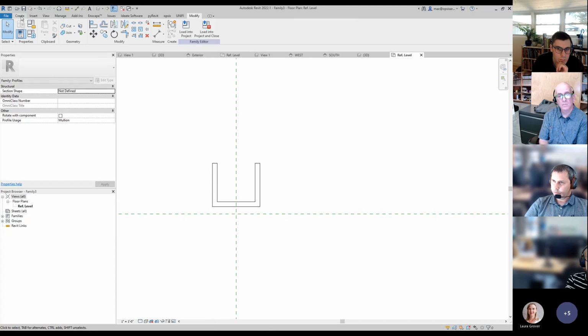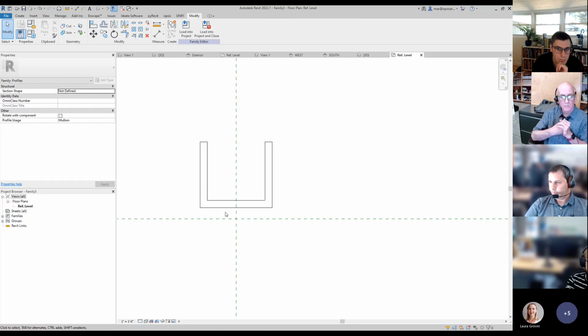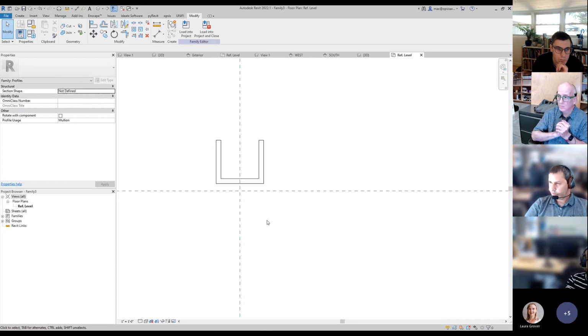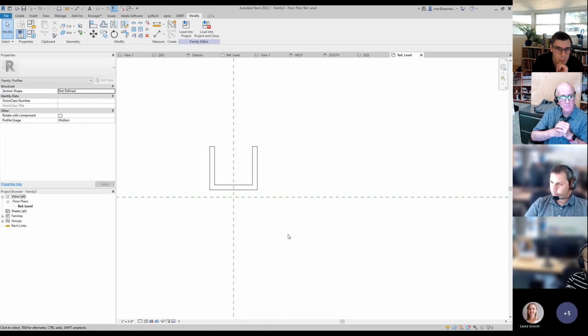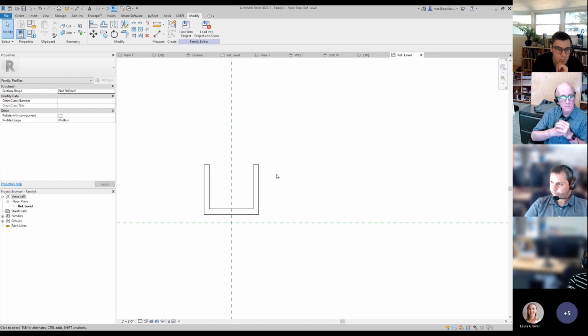And if you wanted to create an SSG mullion, a structural silicone mullion, then you create your half inch reveal here for the panels to trim to, and then your larger mullions in the back. So the panels will trim to those edges, if that makes sense.